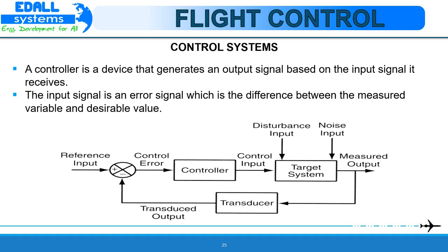So feedback is a property of a system by which it permits the output to be compared with the reference input to generate the error signal based on which the appropriate controlling action can be decided. So depending upon the nature of the controller, it is required to reduce it or amplify it or change its nature, that is make it discrete from continuous type of signal. This changed input as per requirement is called a reference input, which can be generated by using reference transducers.